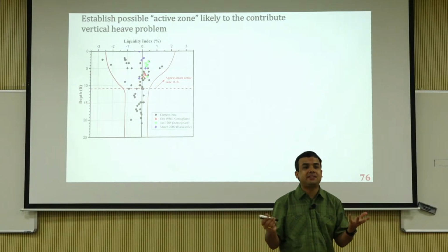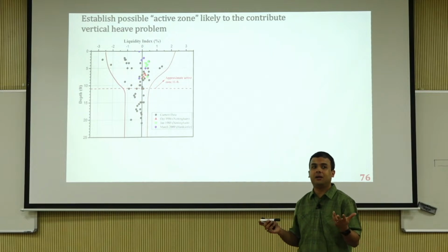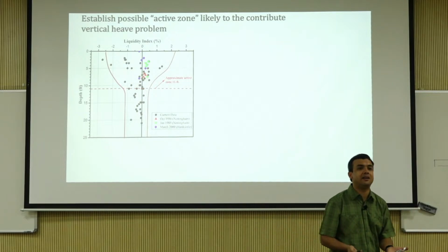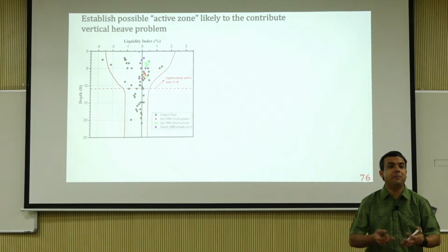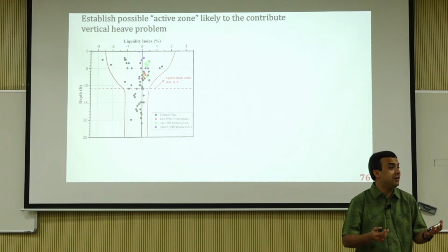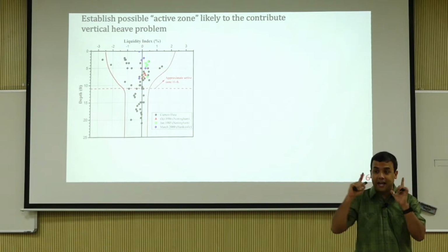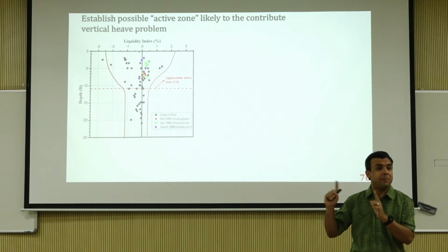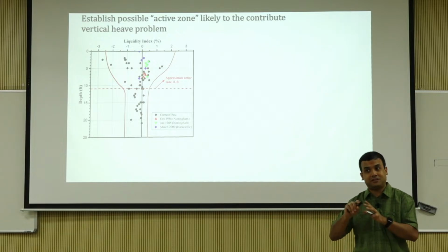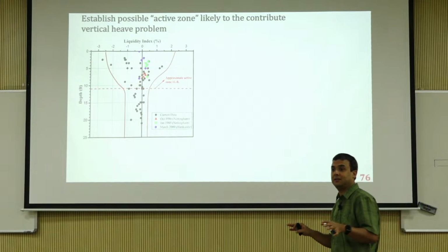Can you replace 3.5 meters of soil? Can you lime stabilize 3.5 meters of soil? Can you chemically stabilize 3.5 meters of soil? You can't. So the answer is, you cannot stop this soil from expanding. That's just the truth. You have to live with it.